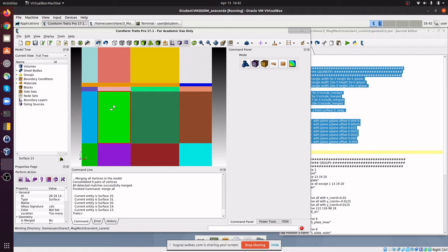This models a so-called stranded coil, which in practice would mean that the coil is made up of very thin litzes, so a litz wire. The reason for the litz wire, of course, is to prevent eddy currents. So by assigning 0 electric conductivity to this coil region, we prevent eddy currents, but not in this plate material, which consists of maybe iron or aluminum, some electrically conducting material.